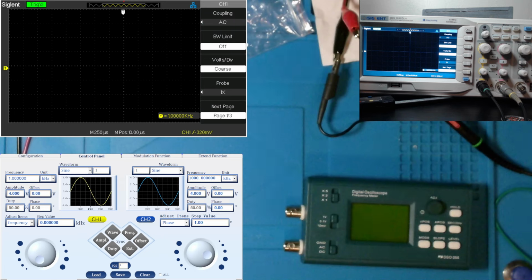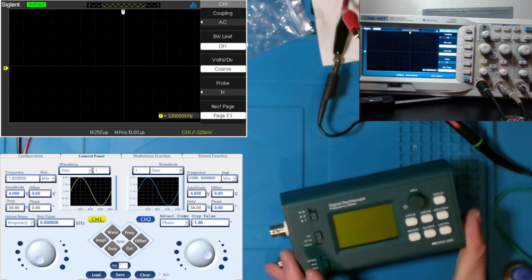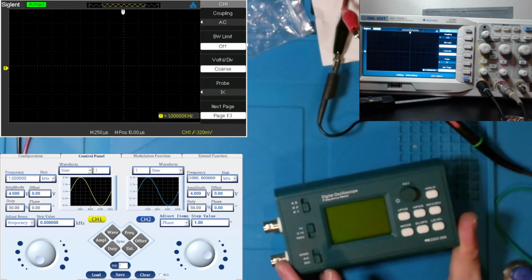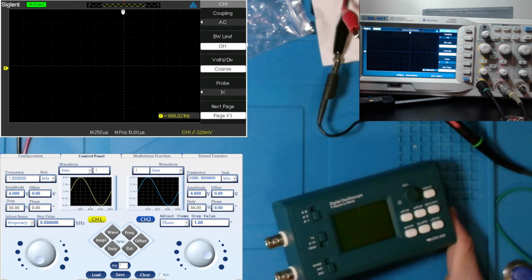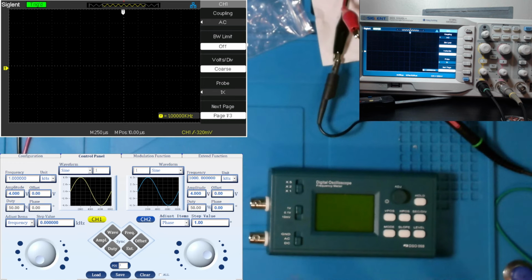Okay, we're going to start demonstrating something that I think is actually super cool. If you're not going to get cursor controls and stuff like that on something like this, automatic measurements, etc. The bandwidth on this is so minuscule, you're not going to see AM modulated waveforms, but as well, Lissajous patterns. For those of you who do or do not know what those are, I think they're absolutely wonderful, and they can give us quite a bit of additional ability to troubleshoot not just the phases of our signals, but also potentially components as well.